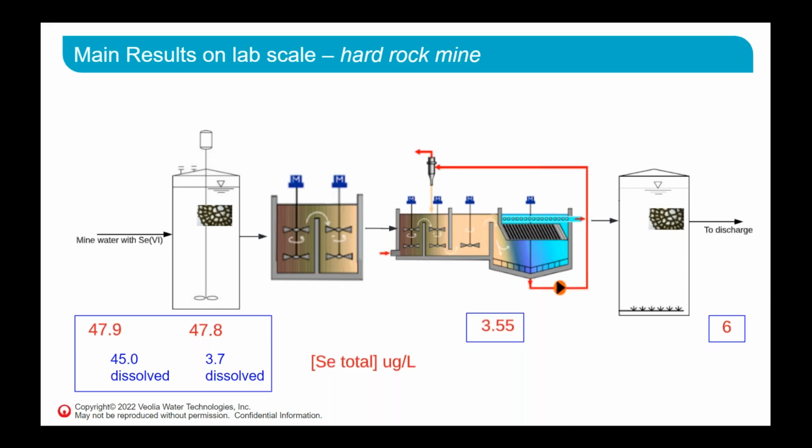So we need to accumulate water out of the reduction MBBR. Then this water is treated by batch, and we need to take this water and pump it back to the Reox MBBR. So all of a sudden, the MBBR sees a different quality of water, and it has not been fed for a couple of days by the time we accumulate the water for the clarified water production.